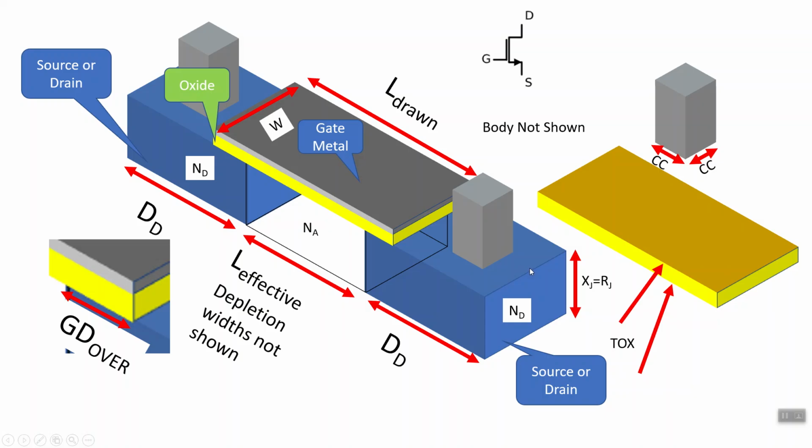All right. And so in some ways, the parasitic devices are controlling the speed. I'm just picking on this area here. We usually think of the drain capacitance as something that needs to be charged and discharged. Many times the source is tied to ground, and so the PN junction is shorted, and there's no capacitance to charge and discharge.